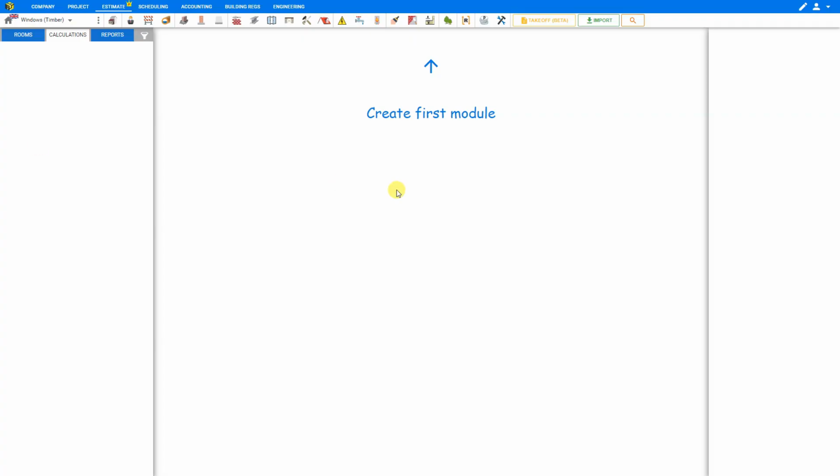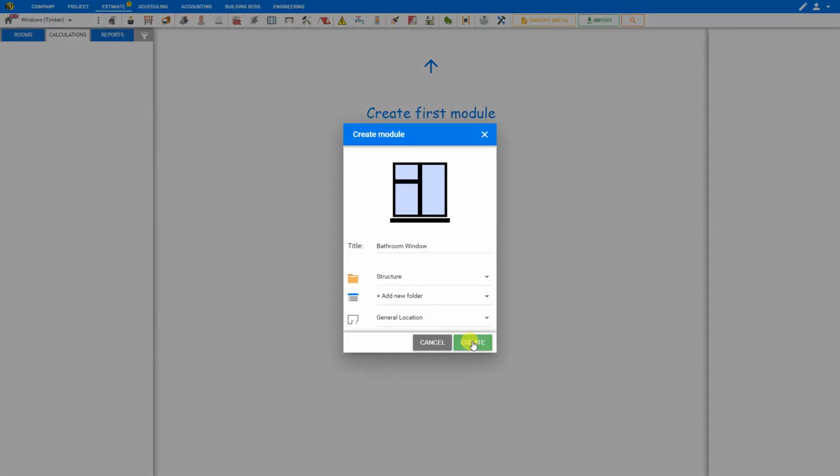To access the new module, first we'll go to the Openings category here in the top module toolbar and select Openings. The new Window Designer module is more advanced than the previous Windows module and allows you to configure any style of design, including openings, handles, glass, and everything else in great detail. To open the module, click Window Designer and create.